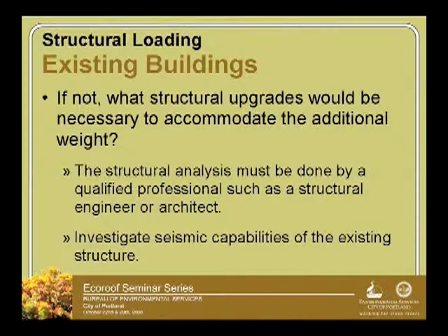I think it's worth getting a hold of them, and we're going to have some structural engineers on our resource list on the web that you'll be able to call and try to get some of that information from. Either obviously hire them to come out and do an evaluation. And then if they give you a go, no-go on that, then you can say, okay, it's possible, then what structural upgrades do we need, and have them do a design for you. Obviously some of those industrial buildings are going to be a lot easier because there's potentially open access to those structural members. So the cost for those additional structural upgrades may be less than if you had a full-blown office building where there are drop ceilings and the structure isn't exposed.